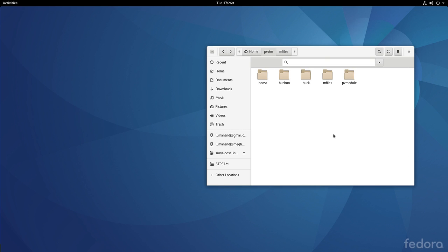In the simulation folder, I have created 4 more folders. The boost folder for simulating the boost converter interface to the PV module, buck boost converter interface to the PV module, the buck converter, and there is an M file here in this folder which will check for reachability of the duty cycle for any given converter. Let us look at the boost converter first.